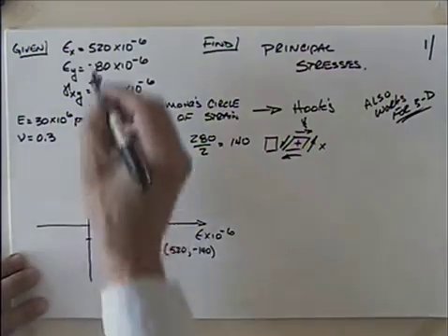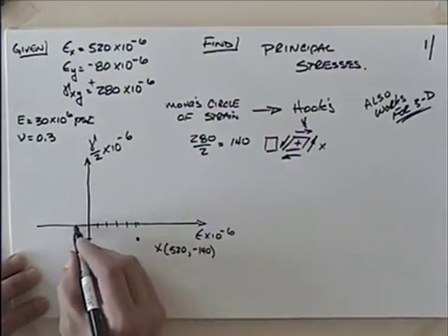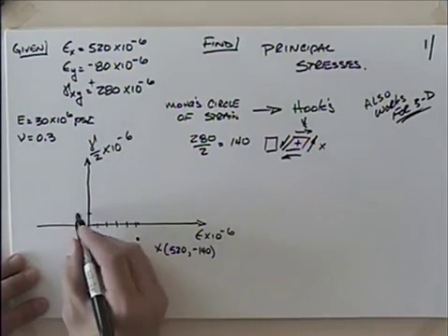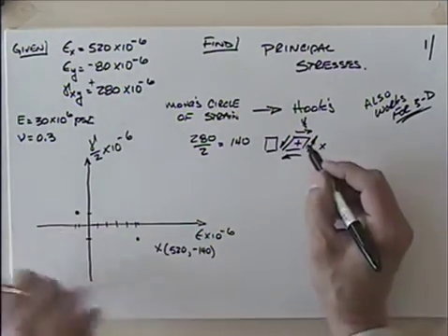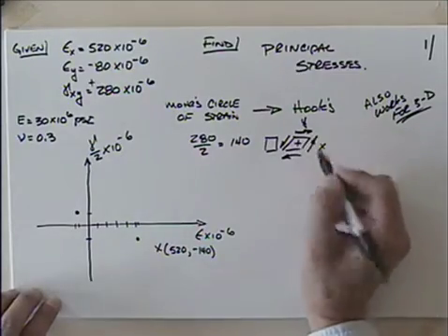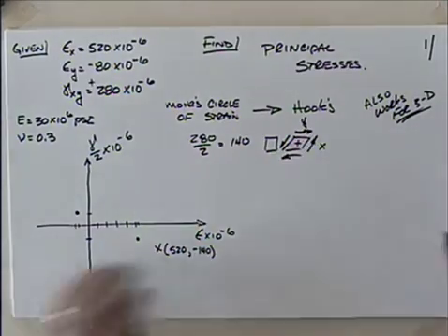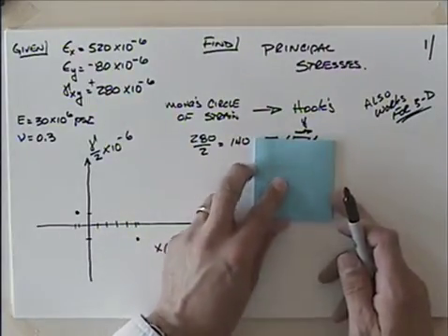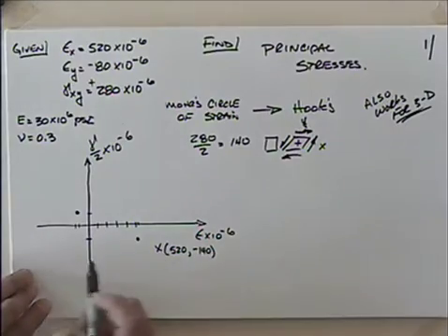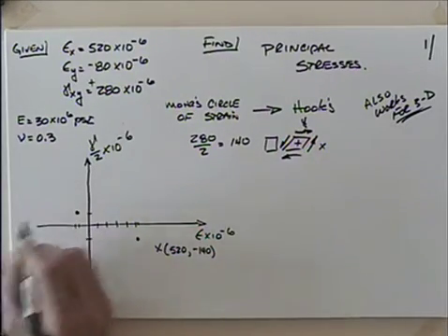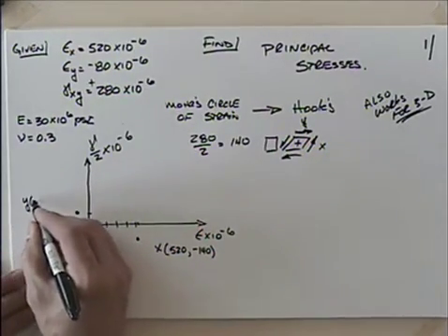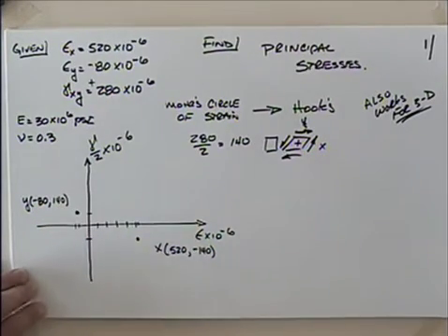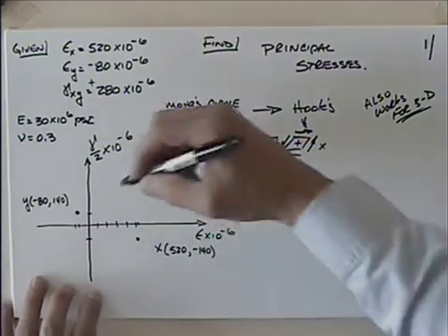Now if I do y is minus 80, so I need to go to minus 80, I'll be about right there, and we would recognize that we probably would be positive. Does that work over here in the y direction? Yeah, the y direction is going to tend to rotate that, looking at just the y. If we look at just the y piece, that's going to tend to rotate it clockwise, isn't it? So with that, I could say that I have y that is minus 80 and 140. And of course, that's times 10 to the minus 6. So there's the diameter.